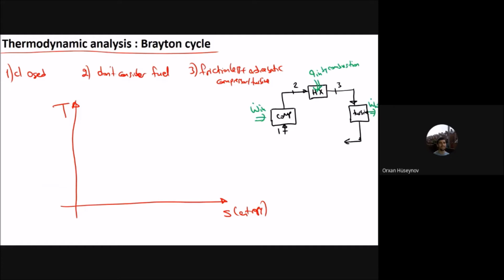make it a closed system. And therefore, I should remove the heat, so that I remove the heat from the system, that Q dot out, or it can be Q out, it doesn't matter. And then you go back to the initial cycle, and this one will be 4. You can see I start from 1 and compress it from 1 to 2, and then 3, and then 3 to 4, and then 4 back to 1. Okay, and this is the first important stuff.